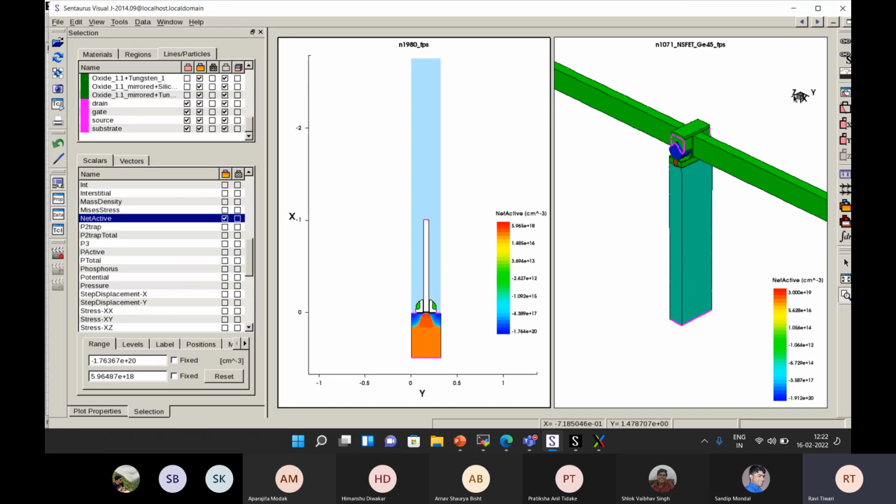So if you take a slice and check how much current is coming from one slice, you can multiply the current by the number of slices and get the actual current coming out of a 3D device. You don't really need to simulate the 3D device unless it is not symmetrical. If it is symmetrical, you take a slice, do the simulation, get the measurement out, multiply with the width, and get your IV for a 3D device.